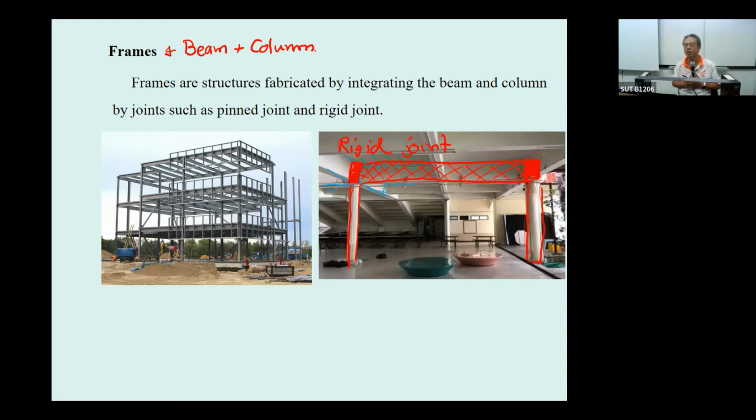And later, after we know the size of the beam and the column, we put them together and reanalyze it and check that the size of the beam and the column are able to resist the forces. Okay, that's what we estimate from the structural plan.